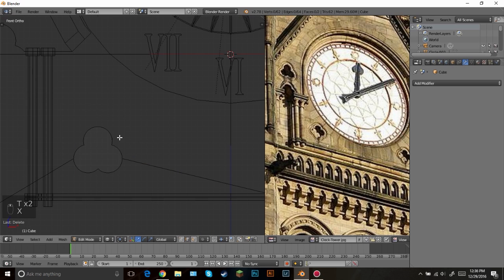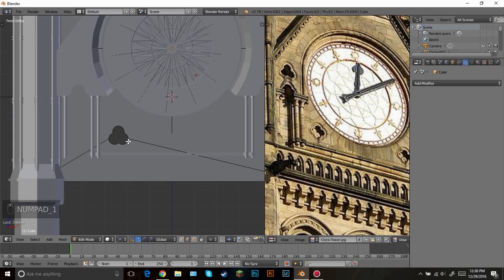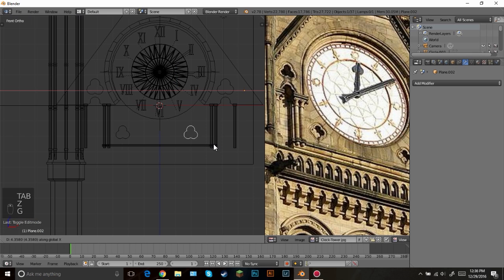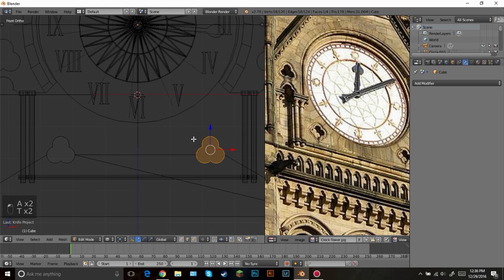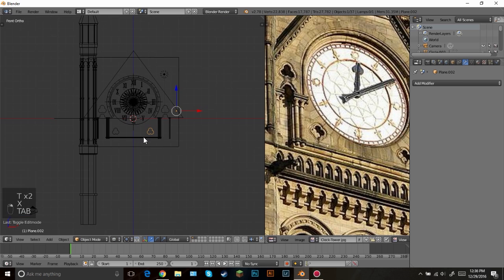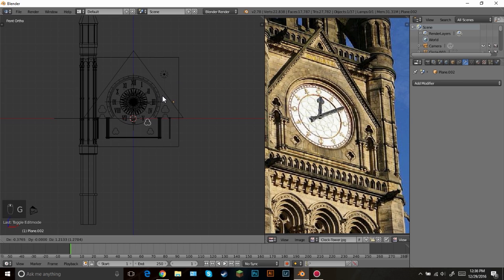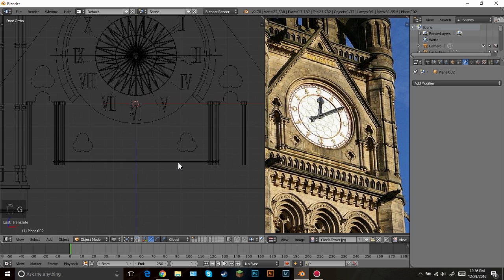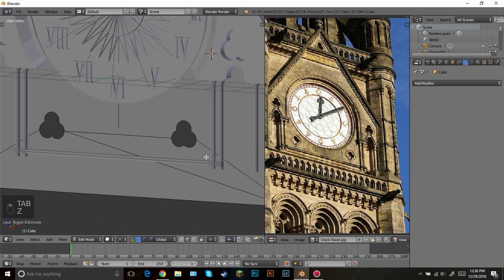There we go. Yeah, and then just delete the faces. Oh, that looks much better. Before it was totally messing it up. Alright, so now we'll do the same thing over here. So right about there, yep, go into edit mode, select everything, and click knife project, and delete the faces. Okay, and then I think we're going to delete this guy. I don't see any other, oh, there's one up there, so I'll just move it up there. And then, yeah, good. So now everything is good. The geometry is a little messed up, but that's okay.